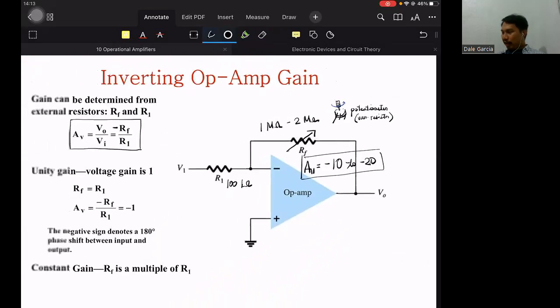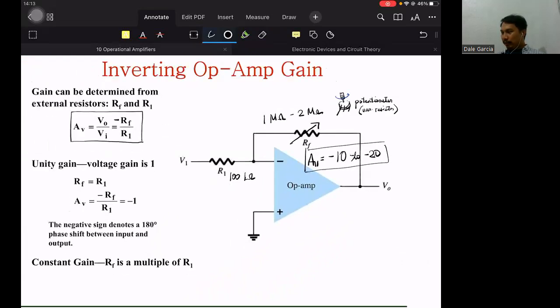Does the operational amplifier have loaded, unloaded, or with-source conditions? No need, because there's no absolute gain. Remember, the input impedance is infinity.